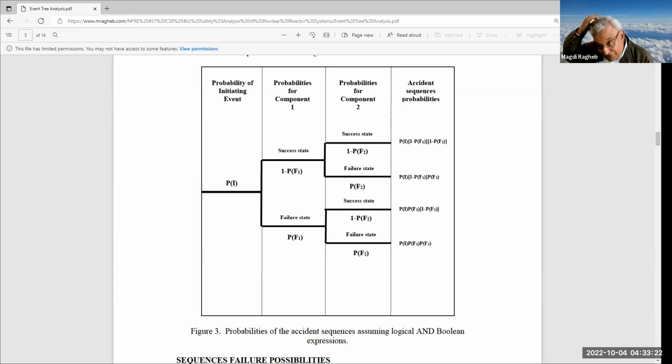Or you have maybe the starter on the car would not start your car 9 times every 10 times you start the car. So when we design meaningful engineering systems, the probability of failure has to be less than maybe 10 to the minus 3 or 1 in 1,000 or 1 in 10,000. So the probabilities of failure here for meaningful components in engineering should be very small. Otherwise, we cannot sell them. Nobody will buy them. No one would want to even operate them. So in that case, you'll find that those probabilities of failures here are very small.